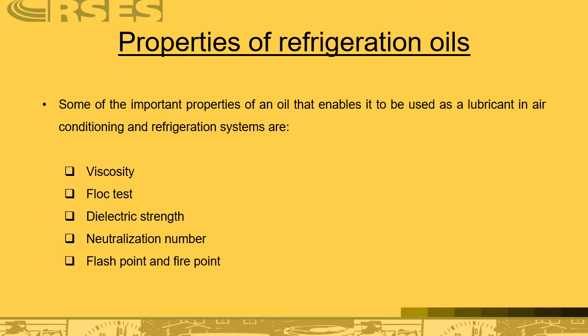Properties of refrigeration oils. Some of the important properties of an oil that enable it to be used as a lubricant in air conditioning and refrigeration systems are the viscosity, the floc test, the dielectric strength, the neutralization number, flash point, and fire point.